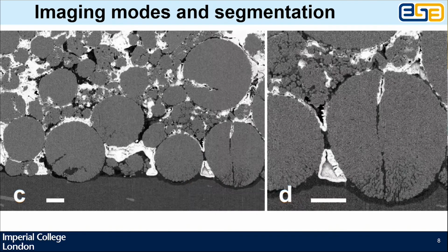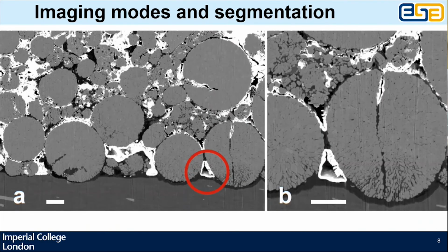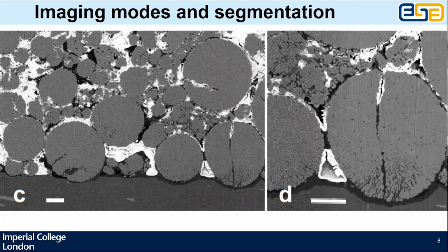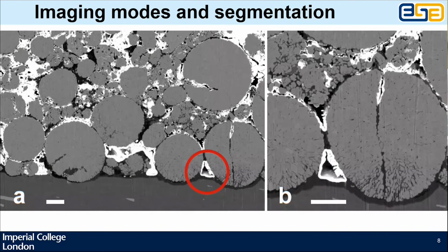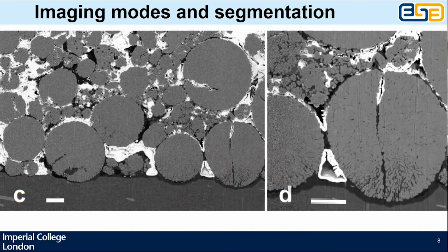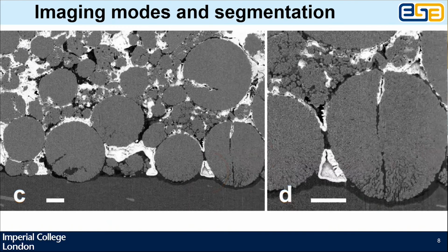So if you look at the red ring around that feature there, it's clearly a hole that we haven't managed to totally fill with platinum. The in-lens backscattered detector sees the back wall of that thing very easily. So what we do is we use multi-channel convolutional segmentation methods. So just pass this in as an image with 2 channels, and then apply segmentation based on convolutions of those 2 channels. So here we go. Here's an overlay of the resulting segmentation.